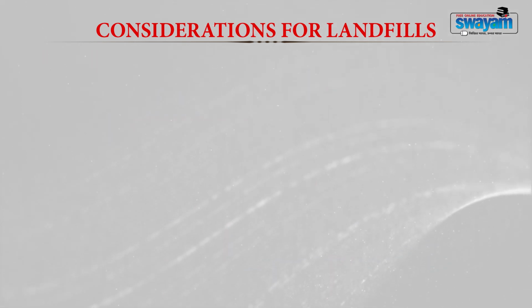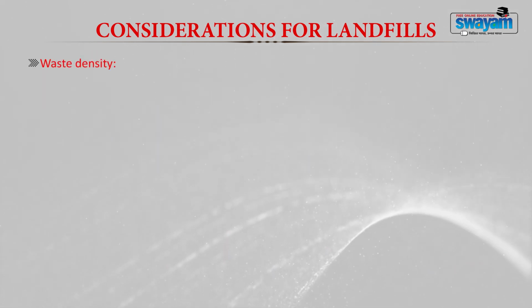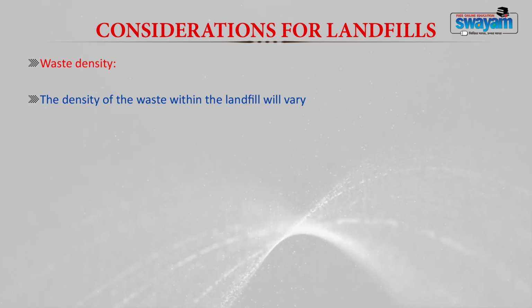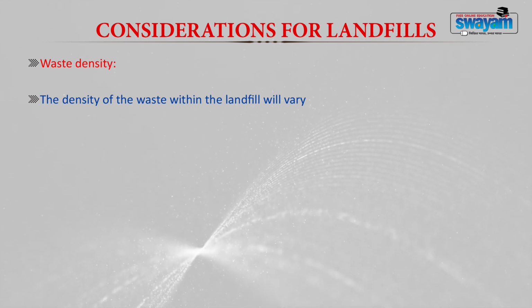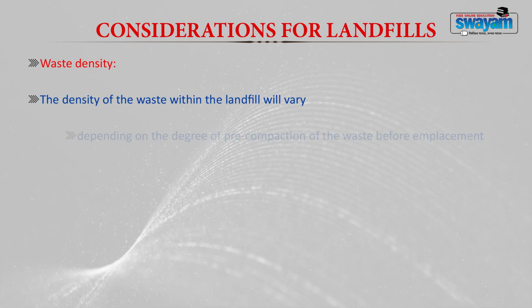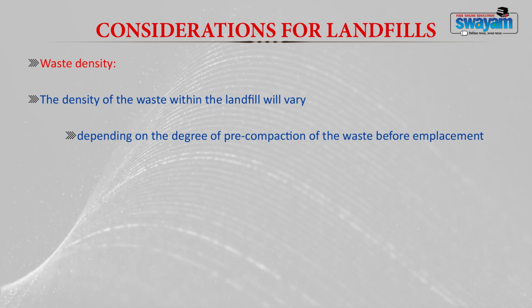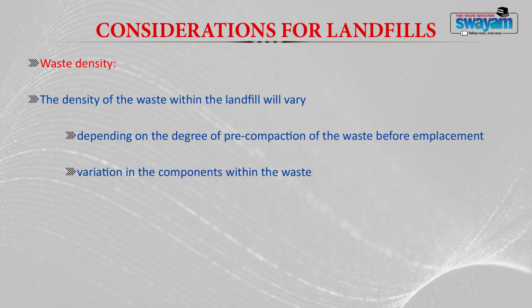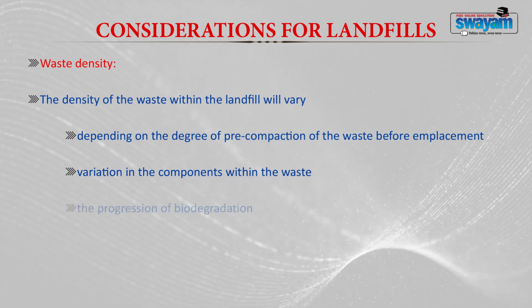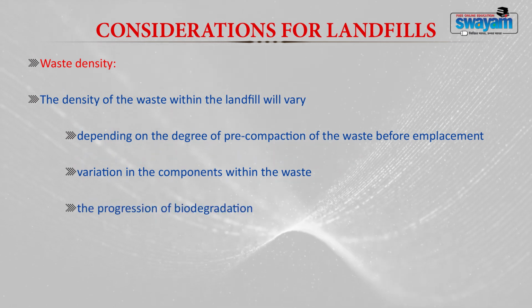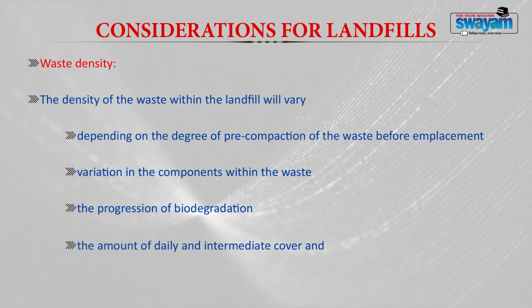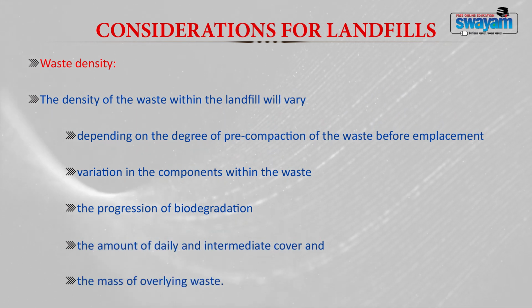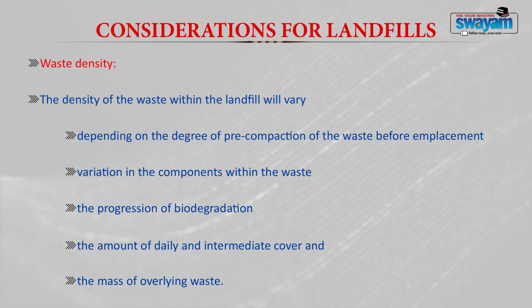The second consideration is your waste density. The density of waste within the landfill keeps varying due to various factors. 1. The degree of pre-compaction of the waste before emplacement. The variation also occurs in the components within the waste. Then the progression of degradation, the amount of daily and intermediate cover, and the mass of overlying waste. All these factors determine the waste settlement in a landfill.